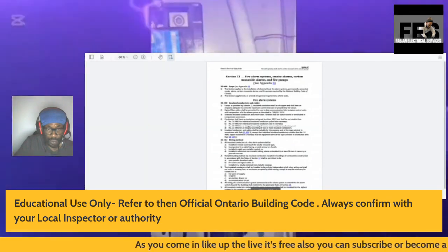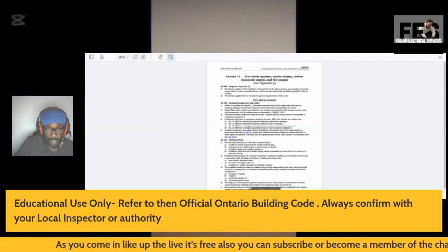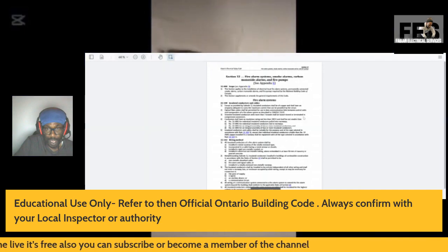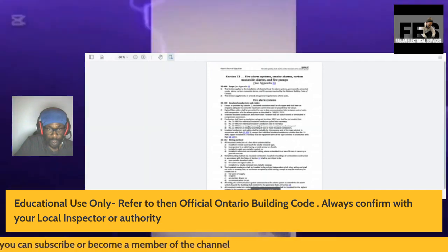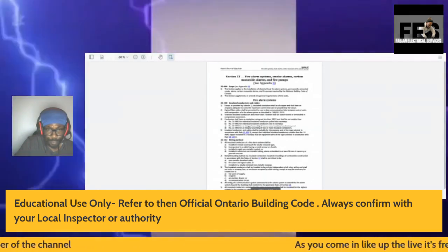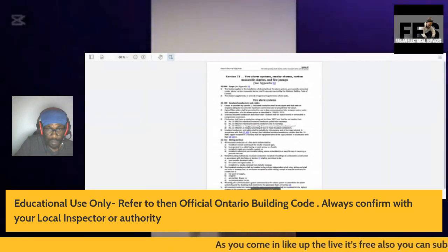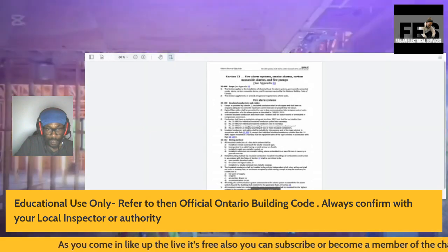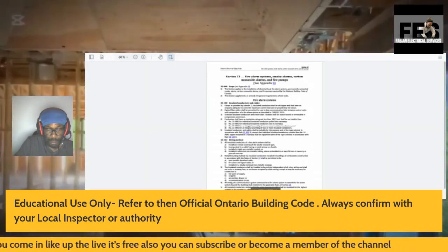Stranded insulated conductors with more than 7 strands shall be bunched in or terminated in connectors. Conductors shall have an insulation rating not less than 300 volts. Again, this is the fire alarm system.